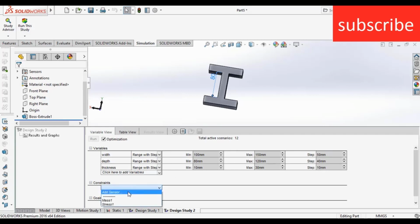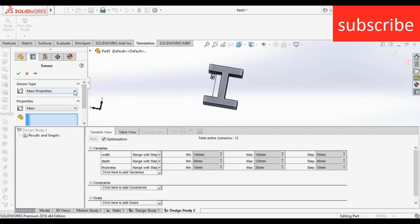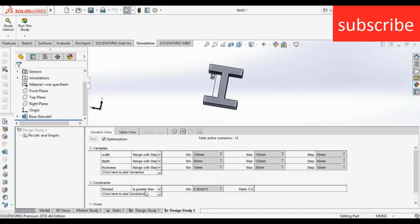Now click on add constraint, click on add sensor, click on simulation data. Remember, you can only use simulation data when you have already run the simulation. If you haven't, then you can't do this design study. Click OK. Now here it is asking what the minimum stress, maximum stress, or in-between should be. I want my stress to not go beyond 50, so click on less than, because I don't want my stress to go above 50 Newton per mm square.